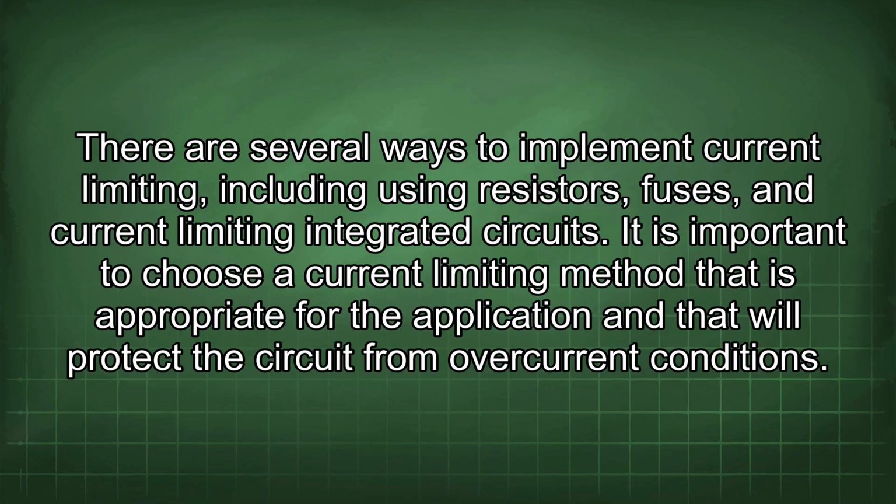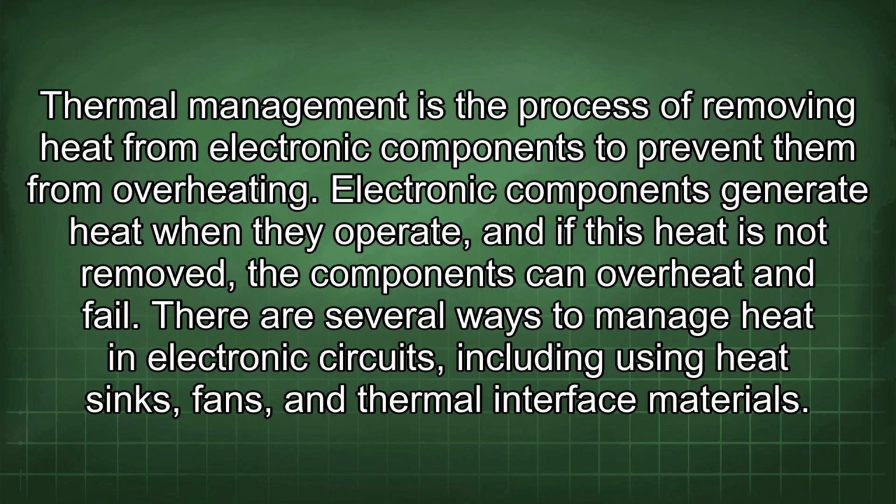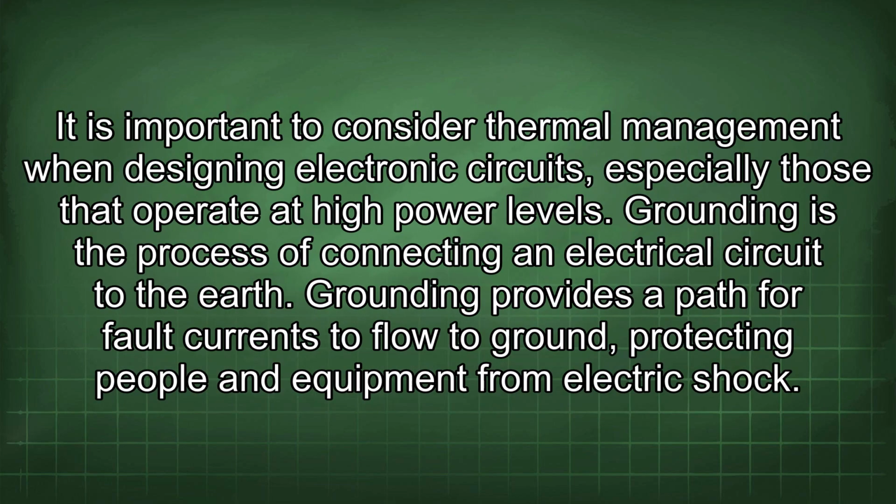circuit from overcurrent conditions. Thermal management is the process of removing heat from electronic components to prevent them from overheating. Electronic components generate heat when they operate, and if this heat is not removed, the components can overheat and fail. There are several ways to manage heat in electronic circuits, including using heat sinks, fans, and thermal interface materials. It is important to consider thermal management when designing electronic circuits, especially those that operate at high power levels.